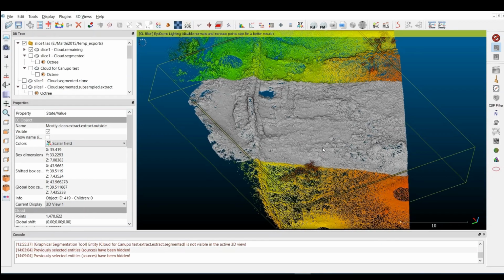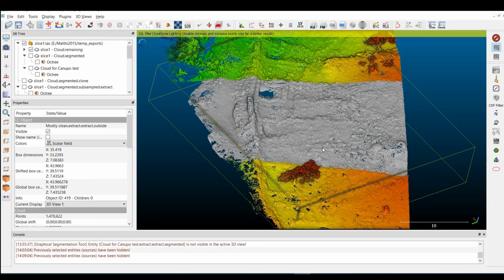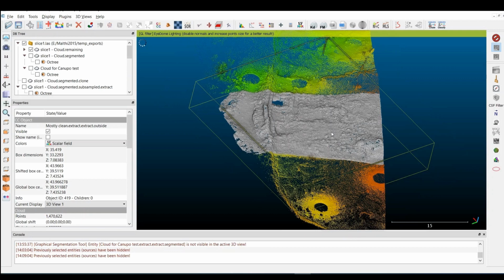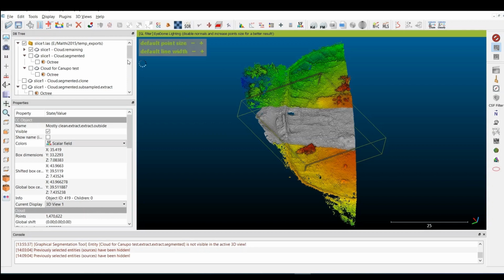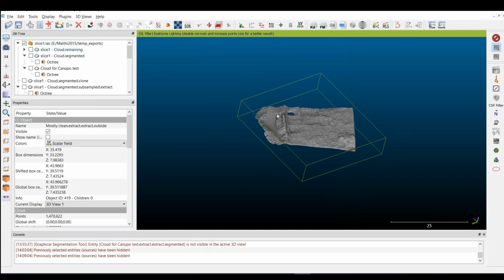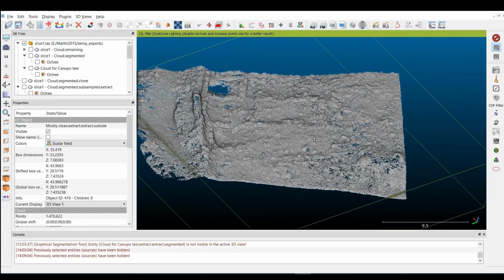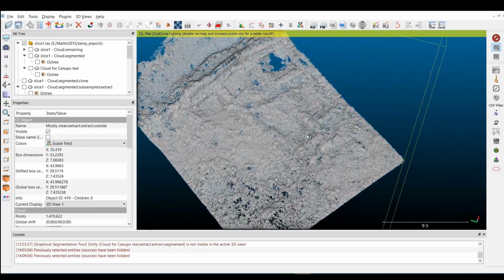So if we think about these slices we were talking about earlier, you're going to want to think about how you can keep track and label each of these slices in a sensible way. So since we're at slice 1 and I've sliced this into 3 pieces, it might end up being 4 up here, but I may end up labeling these A1, A2, A3, maybe A4. And so this one I might end up calling A2 preemptively. Obviously it's having a hard time rendering all that, but this is what we will proceed with to create a mesh.